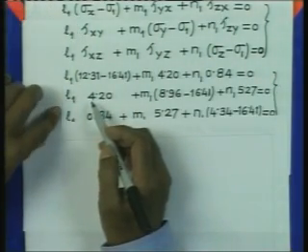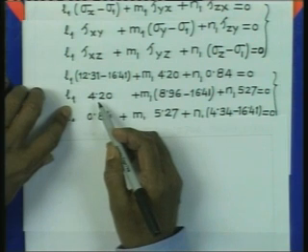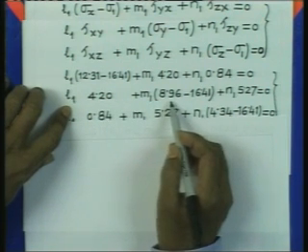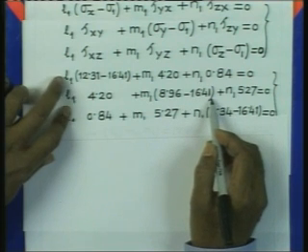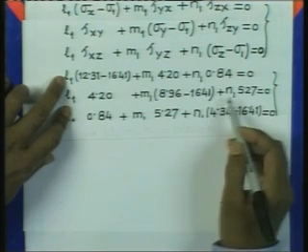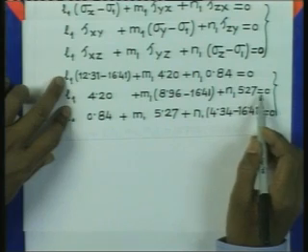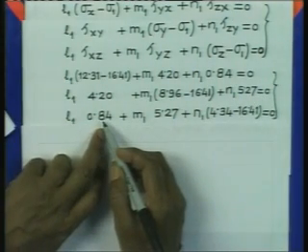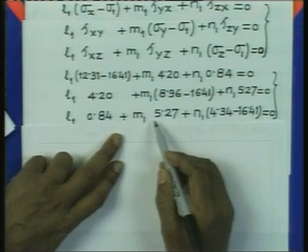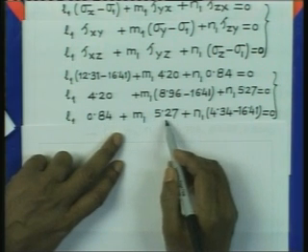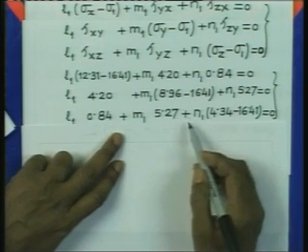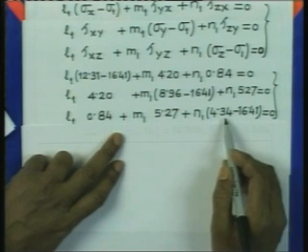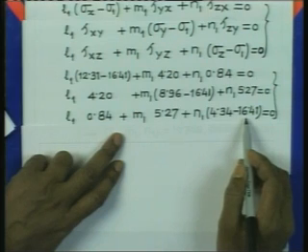Similarly, you have the second equation here, this is tau xy plus m1 into sigma yy minus 16.41, which is the value of the first principal stress, plus n1 into 5.27, and the last equation is L1 into, this is the value of tau xz, and m1 into 5.27, that is the value of tau yz, plus n1 into 4.34, which is the value of sigma zz minus 16.41.